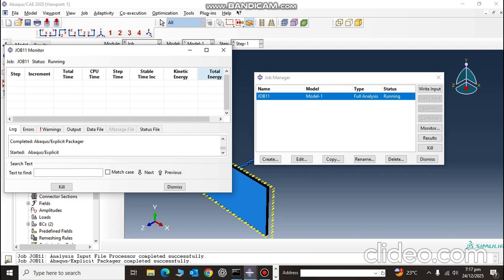And the third error appears when after some time you will notice that the total time is not increasing, so it is coming same, and this is due to the boundary conditions as well. So if you fix the bottom ply, no matter your upper plies are free, the drill will not be allowed to pass through, and the total time will get stuck at one place.